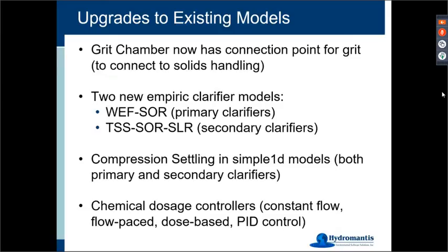We have 2 new empiric clarifier models, one for primary clarifiers that came from a WEF model that was brought to our attention, and we've been using a little bit. It's based on surface overflow rate. And then we developed our own secondary clarifier empiric model that is a combination of several things: solids concentration, surface overflow rate, surface loading rate. It's not a one-dimensional flux model, but it's also not a simple empiric model. It actually does change with different loadings and so on, the performance stuff. So it's a nice in-between version of that.